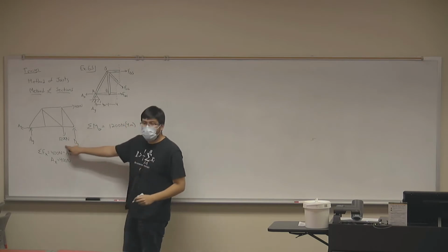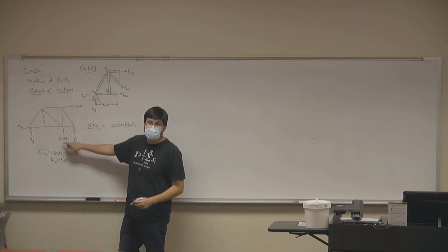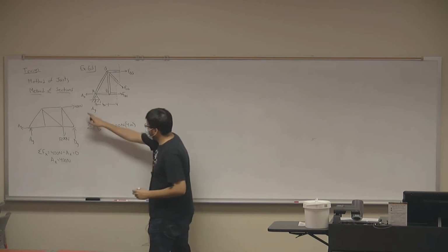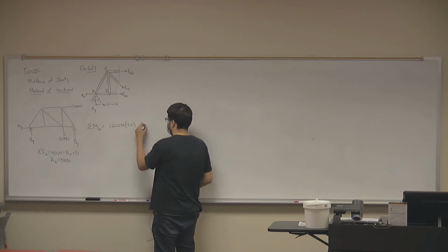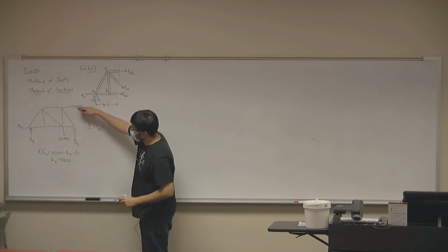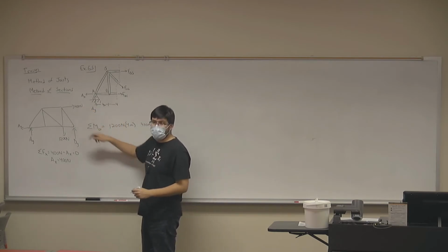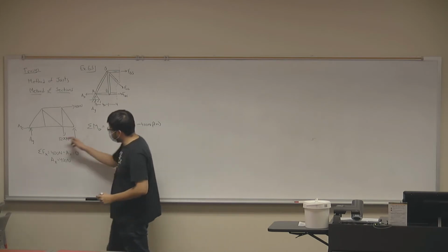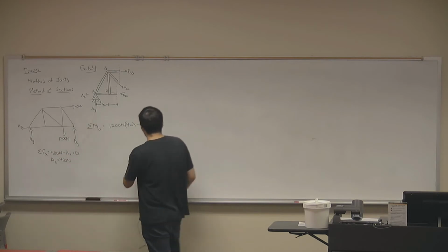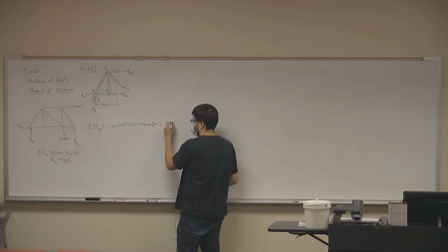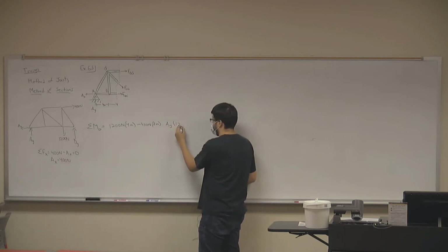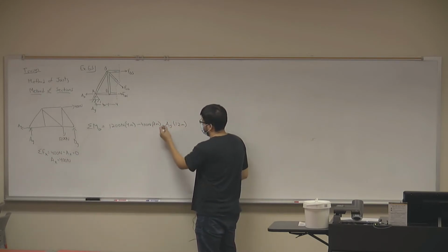Is this a positive moment or negative moment? Positive, because it'll be a counterclockwise rotation. Good. I have a force of 400 newtons acting at a distance, if I remember correctly, of 3 meters in the vertical, right? And is that a positive moment or negative moment? Good. Finally, I have a reaction force AY acting at a distance of 4, 8, 12 meters. And is that a positive moment or negative moment? Negative. And all this equals 0,